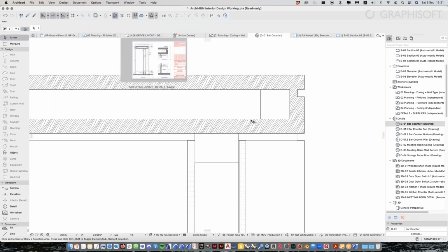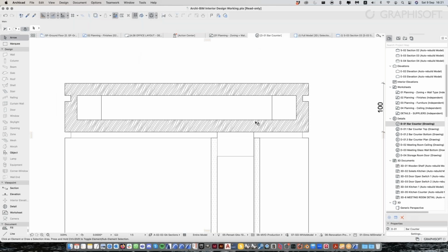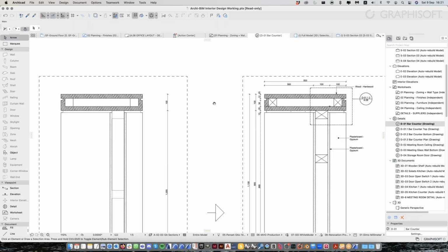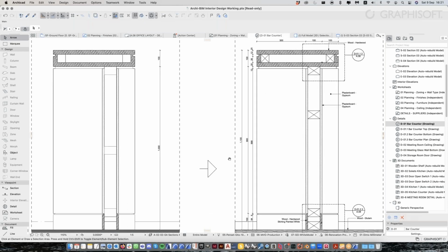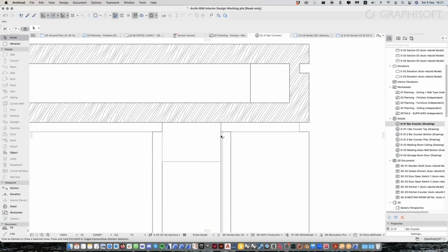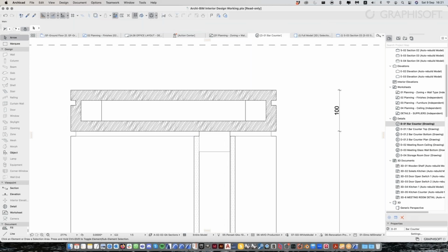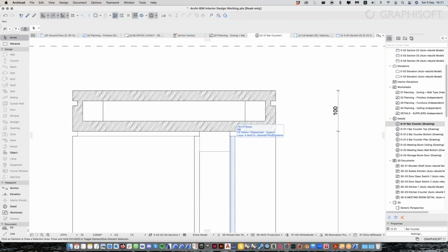That's because a lot of the time we need to balance what we model versus what we need to show. There are really, really tiny details that sometimes it's better to just draw in 2D rather than spending the time to create a 2 mm or 1 mm gap in the 3D model. It will just cost more, it's more time consuming, or if you need to adjust something, it just doesn't make sense to do that.